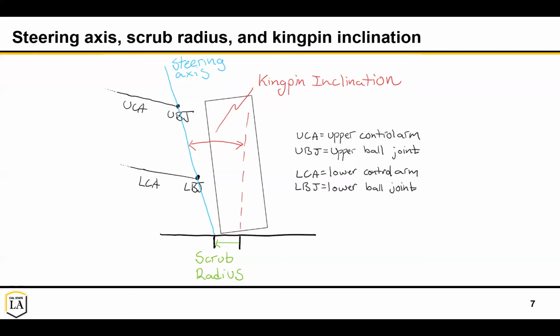So that'll give your driver more feel, especially in this view, where the braking forces will cause moments. But too much, and the braking loads will increase in your tie rod and your steering system, which are holding these. So you might think about having that in tension instead of compression, so that it doesn't buckle under compression.